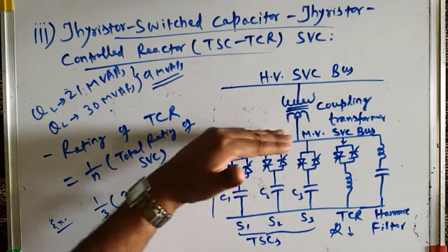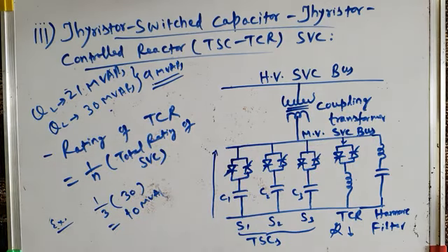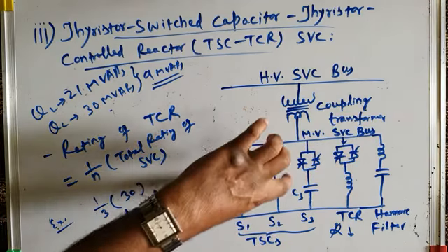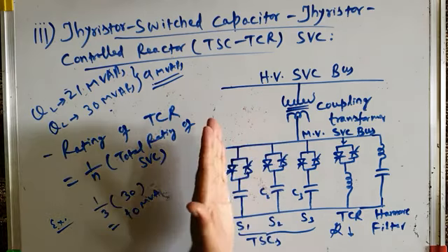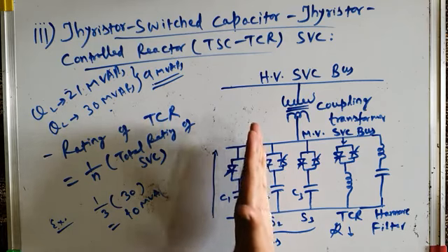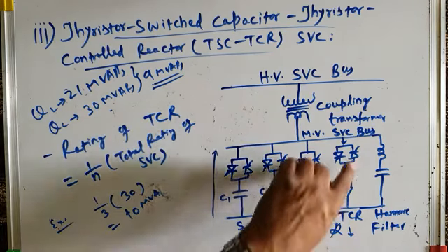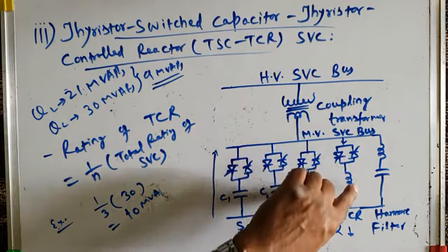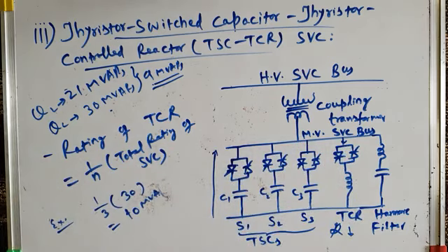The additional or surplus leading wires are absorbed by alpha control. If S1 and S2 are turned on, say earlier only S1 was switched in, now in a discrete step, in second step, S2 is also switched in. Then again, alpha control of TCR is done and it performs the continuous reactive power control.